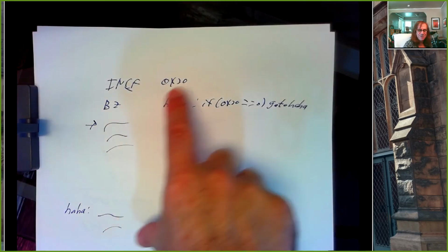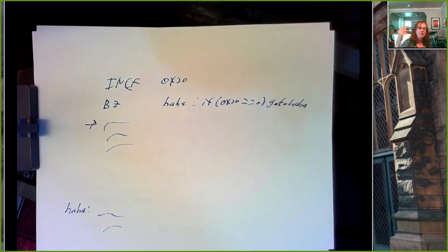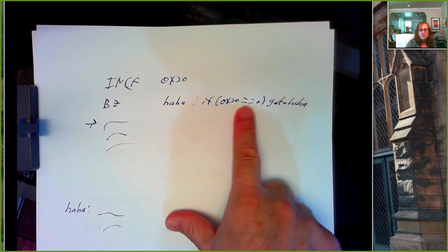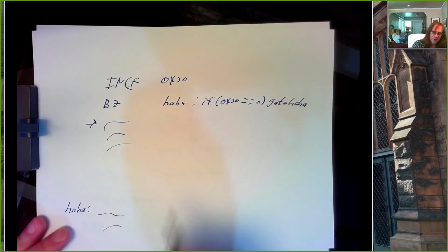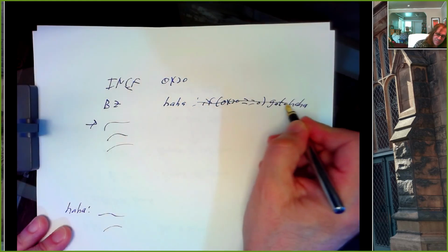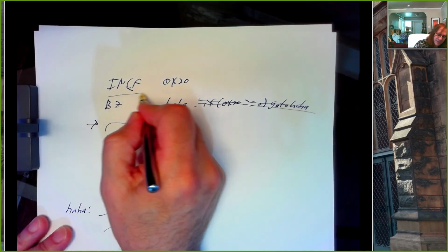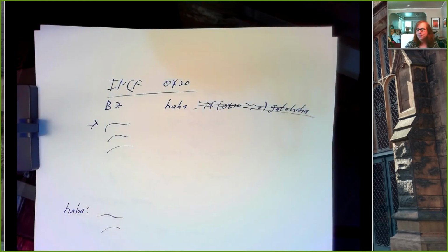So if I increment file register 20 and I store the result in the W register, right, then it's going to say, okay, so is the W register equal to 0? And it may not even be a result that I stored somewhere. So it's really just whatever the last operation was that you did, did it result in a 0 or a non-zero value?